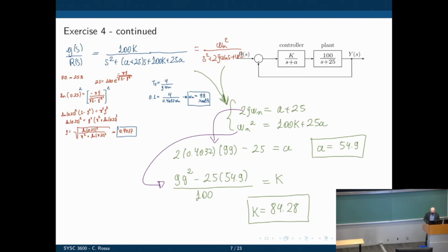different, but it doesn't really matter because what is happening is if we add a number here plus B, what are we doing? We are scaling the transfer function. A transfer function that would have a response like that will now have a response like this, but it will follow exactly the same shape. The shape is only dictated by the denominator of the transfer function, by where the poles are. So if you add anything to the numerator that is just a constant, we're basically just scaling it up or down. But everything will shift accordingly.